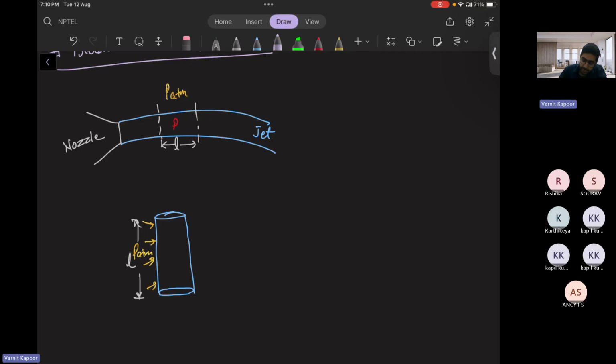And inside, again, you will take a projected area as we did before. So for the cylindrical surface, my projected area is something like this rectangle. Inside it will be pressure P, and outside P atmosphere is acting. You need to find this P value or delta P in terms of gauge. We can observe very clearly that there won't be any surface tension at this point and this point. Why?